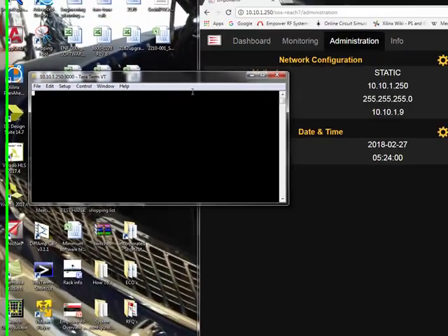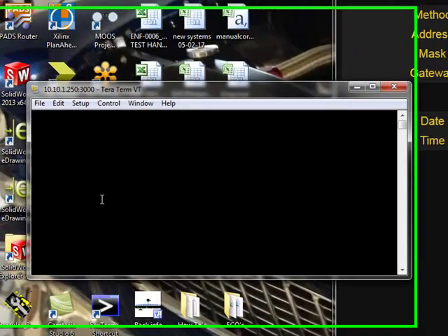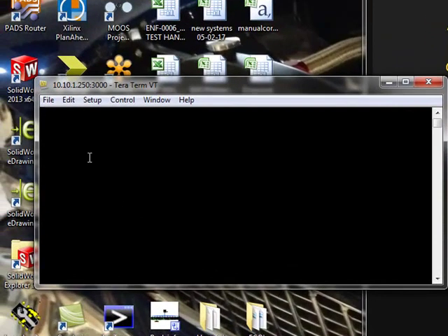One of the first things that we'll notice is that in the web GUI, we've changed from control mode remote to M2M, and it's disabled the commands locally from the web GUI because we're in an M2M connection mode. This is part of the arbitration between the local GUI, the remote GUI, and M2M. M2M has the highest priority.